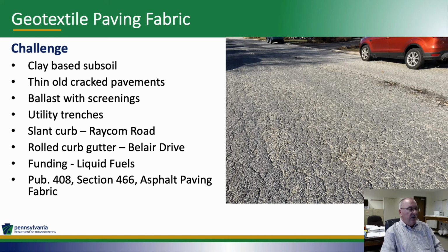So the challenge that we faced with our roads here in the area is due to a clay-based subsoil and thin, old, cracked pavements. Some of the roads that we dealt with this year were ballasted with screenings. You'll see in some of the photographs there was a utility trench down the side of the road, and we had different types of curb. On one road we had slant curb, on the other road we had rolled curb and gutters.